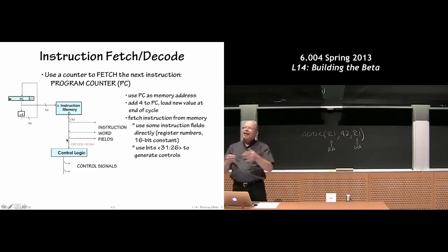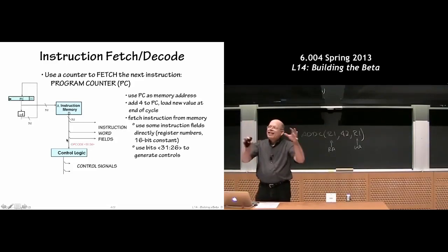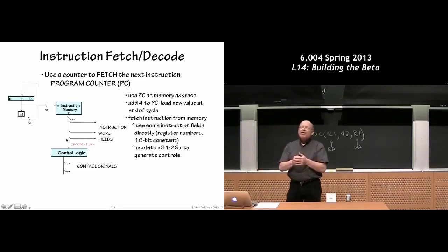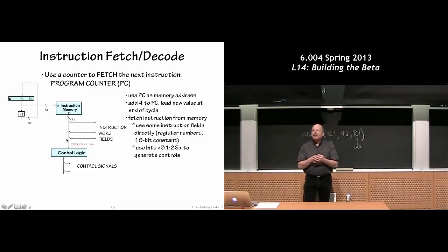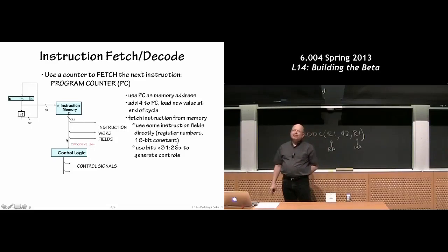And you would say, well, couldn't we pick a clever encoding so that the 5-bit ALU field was exactly somehow embedded? We've chosen not to do that, but with a cleverer choice of encodings we could have simplified the control logic. I think you'll discover that if you implemented the control logic not as a read-only memory, but instead as just a bunch of discrete logic, that discrete logic is actually only a handful of logic gates, so it's not very complicated. The transformation from opcode to ALU function code is actually pretty simple.